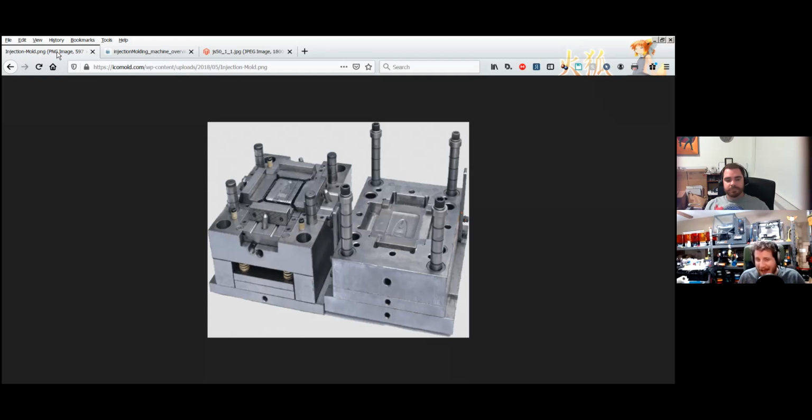So you're looking at 5 layers at once. It's nutter butters to see this happen. It's comical when I watch printers like the Fusion 3 lay down 0.2 millimeter layers in really, really high res. We have nozzles that can lay down 0.6, 0.5 millimeter layers, where you get a lot of speed, but you trade off quality. Precision, yeah. Precision, which is a much better term. Thank you. Precision for speed. When you're dealing with smaller layers, it's a lot easier to deal with.